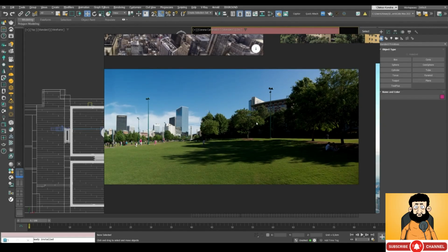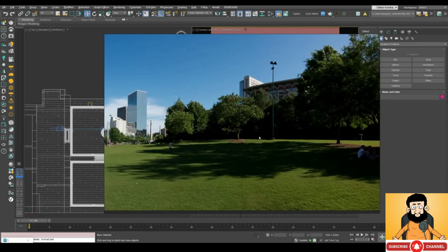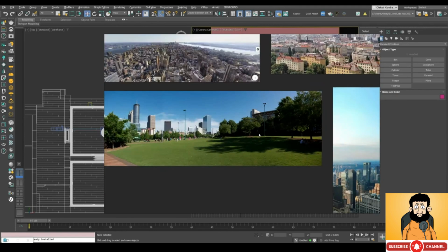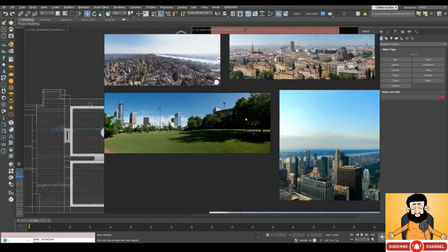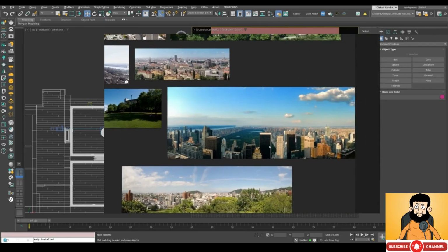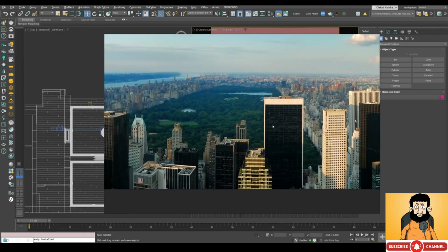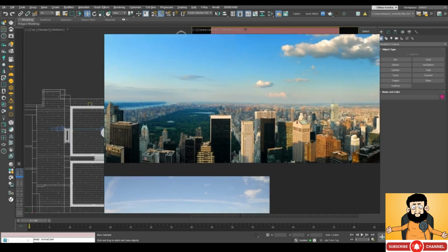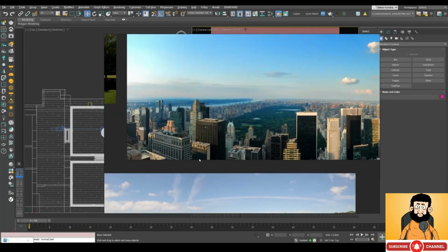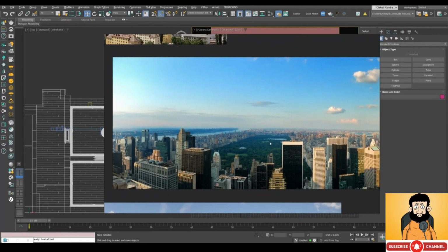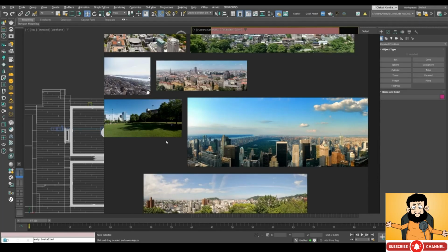If we're talking about an HDRI map with a high dynamic range, its pixels contain halftones, and in that case you'll be able to correct the brightness of such a map. But photos usually don't have a high dynamic range, so the only solution here is to find a new background. And here also we have black facades and very dark areas. And if you think you can correct this image by increasing its brightness, you're wrong. But you can try doing that in Photoshop yourself, that's for sure. Alright, and so the final mistake I'd like to draw your attention to is mismatched lighting.